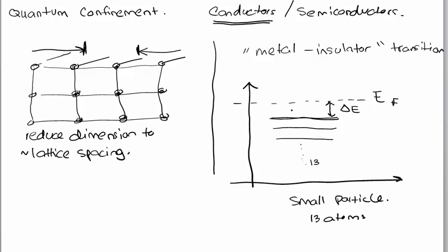All right. Well, what does it take for an electron to hop from the valence band at this level here up above EF, so it can go into the conduction band and conduct? Well, at normal temperatures, this electron can be pushed up by a factor of Boltzmann's constant kB times T. These are thermal vibrations at normal temperatures that allow this electron to jump up into the conduction band.